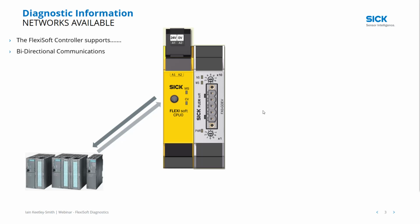You'll notice as well that the colour of the slices here, so the FlexiSoft CPU is yellow and the diagnostic cards are all grey. So how it works in SICK is that if it's a yellow card, it supports safety. If it's a grey card, it's only for diagnostics and non-safe communications.